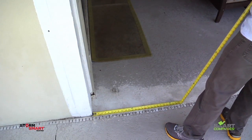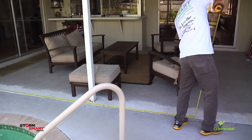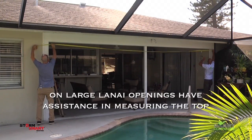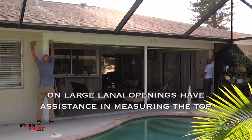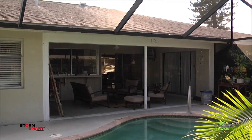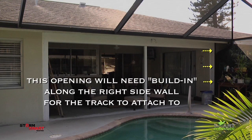Measure the width of the opening as shown. If you have a large opening, we recommend enlisting the help of another person to measure the top of the opening if you can. Again, you're checking to see that the measurements are consistent and the opening is square. This opening will need build-in on the right side.